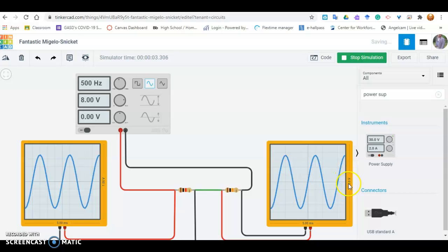So again, over here now our scale is 10 volts in the vertical. So each square or division is equal to 1 volt. If you count from the midway peak voltage, that's 1 volt, 2 volts, 3 volts, a little more than 3.5 volts, just about 3.5 volts. Double that, that's 7. So you're at 7 volts peak to peak here. And then again, it's about 7.3 volts peak to peak there. And you're 0.7 volts or 0.73 volts over here.